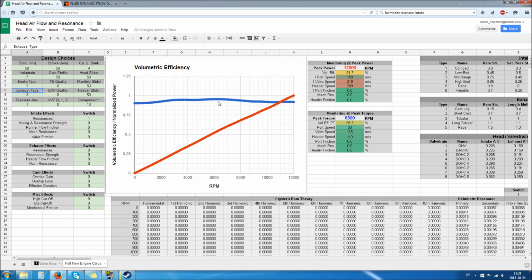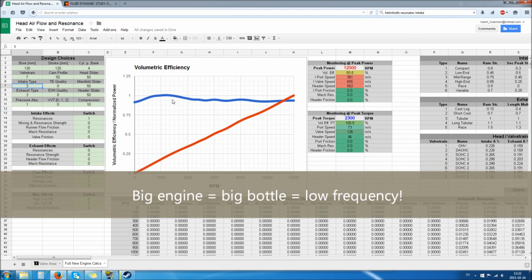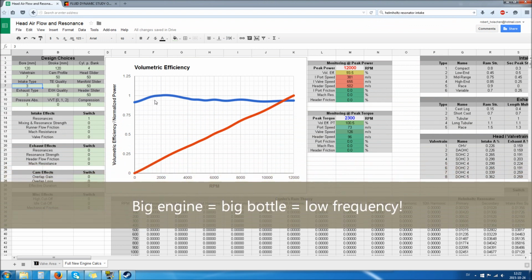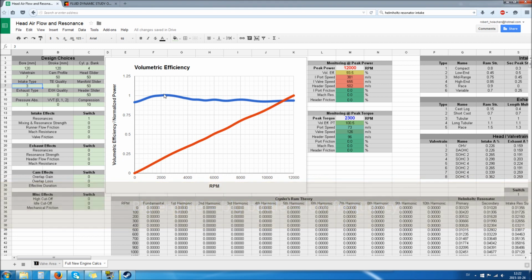So yeah, that is a very important effect for economy and just in general response of the engine, because if you have a big one and you put your foot down in that engine, you can see even with the mid-range intake type, from cruise, you have all the power available. And that is some of the explanation for why the American engines are so torque fanatic. With the pushrod engine design, you can just get so much more capacity in the same sized package. It's probably the main advantage of pushrod engines. And that is enormously helpful to get the grunt down low.